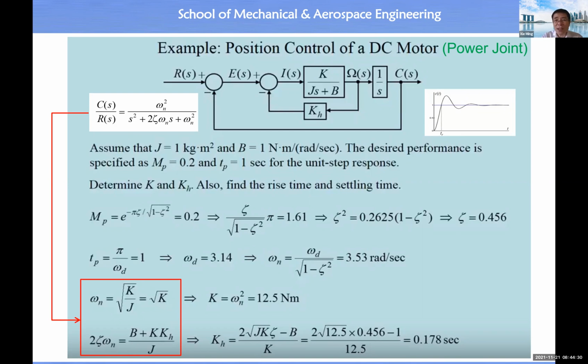Okay, so that means different motors will have different payload, different moment of inertia. So you can choose the value for J. J is the moment of inertia. Okay, so this is just an example. If you have a motor at a different joint, that means the moment of inertia for joint 1 should be very, very large, because this motor will drive 6 links.